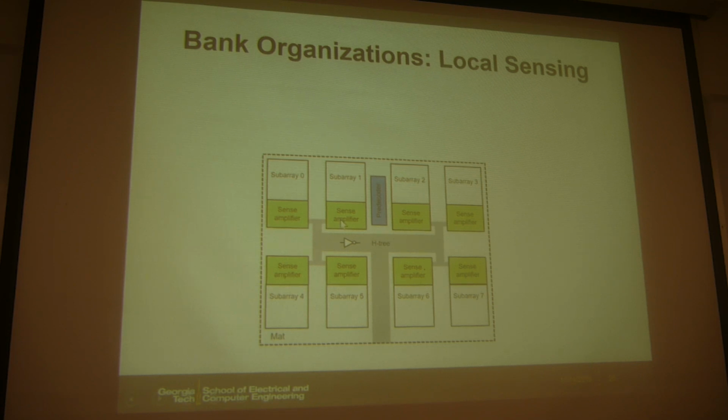This is a typical routing scheme. Those routes are basically wires with buffers, because when you travel long distance, you need to use a buffer or repeater to recover the digital signal. This is a typical way you get those individual bits from subarrays, combine them, and then go to the external I/O.